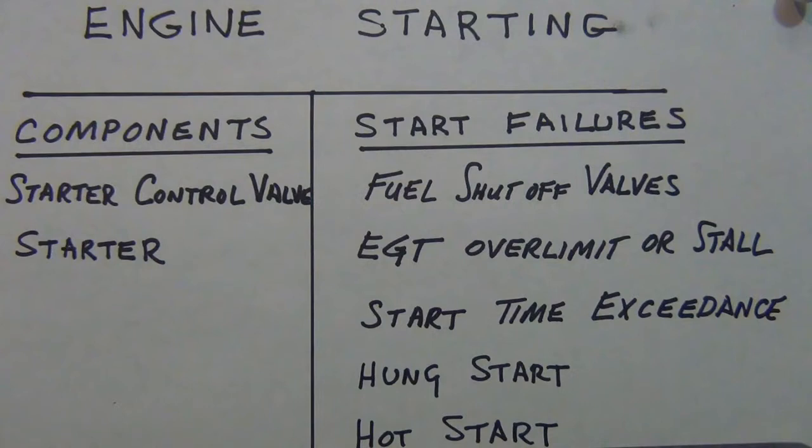And then in manual, it's the same thing: making sure you get the engine master switches off, and then release the manual start push button. And then you have to clear the ECAM control panel and then set that mode to norm. Remember, there's ignition start and you have norm as well. We want it in the norm position. So that's one fault, is having the high pressure shutoff valves not open.